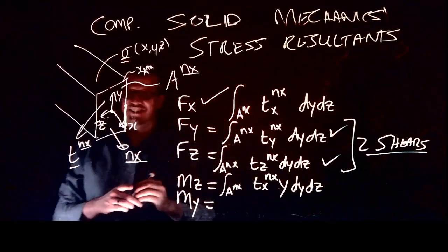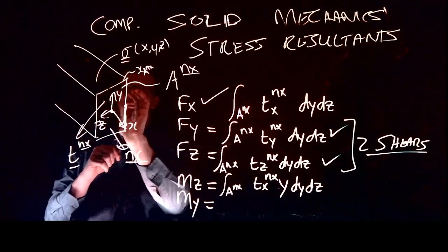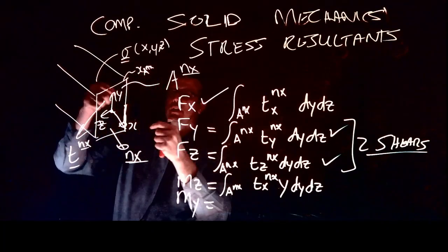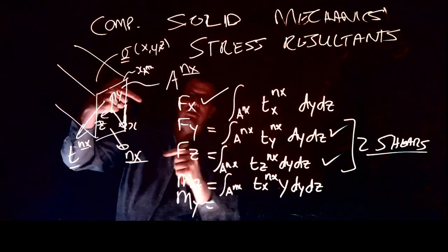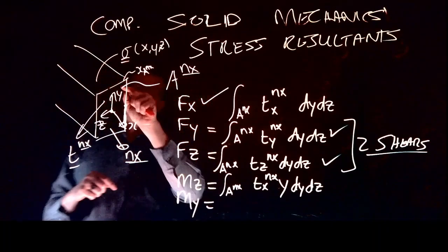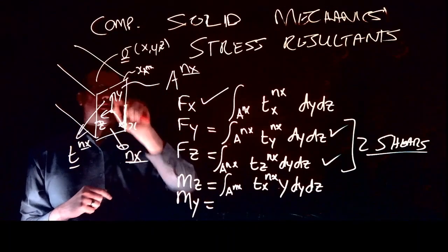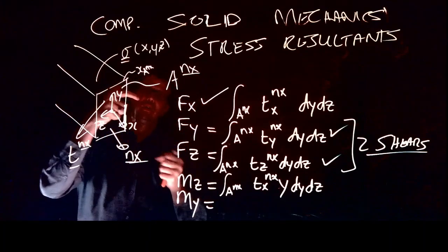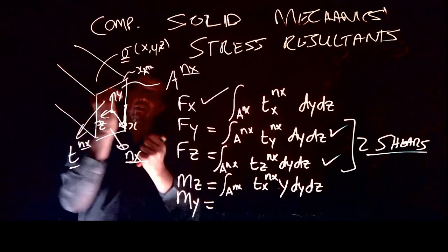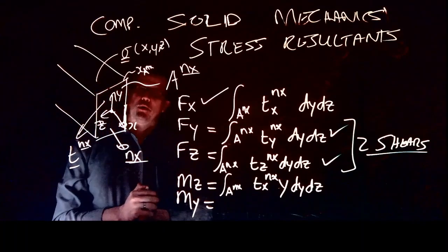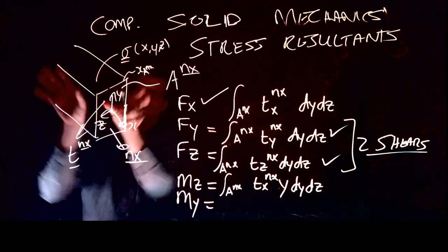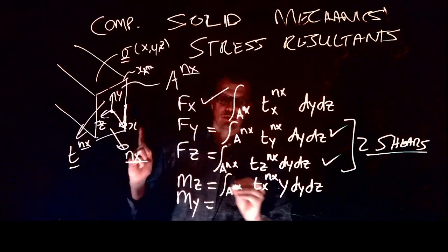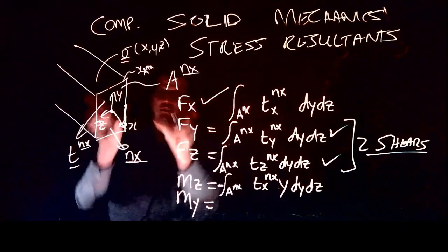First I have to ask myself, what is the sign? Let's say I am pulling this side, so my traction, because the traction vector is expressed in this global coordinate system, has a positive value and the distance is a positive value. If my force is in this direction and my y is in the positive direction, I am essentially applying a bending moment, but this will make this thing go like this. With me? And so that is a negative bending moment, it should be. So I need to put a negative in there because it's this kind of curvature.